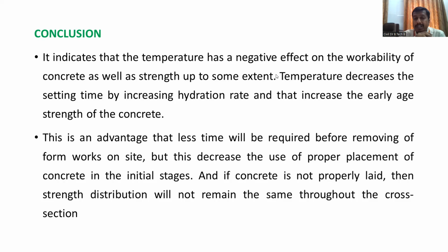That is why the concreting in case of the rigid pavements, most of the time, is done in the evening or at night time. Okay. Concreting in roads is done in the evening if you look. That is due to the temperature effect. We need to consider the temperature effect. Okay. In case of the concrete, fresh concrete.